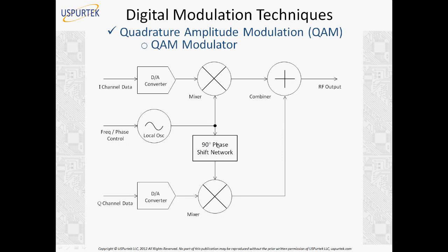Well, there's a question here: are I and Q already 90 phase shifted? Well, they are phase shifted here in the mixer, actually. When you apply the local oscillator, a 90 degree phase shifted signal, that is when you shift, actually. Previously, you just have two streams: I channel data stream and a Q channel data stream.